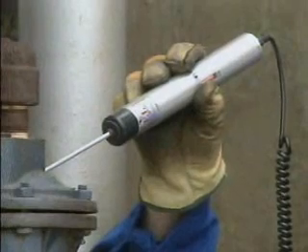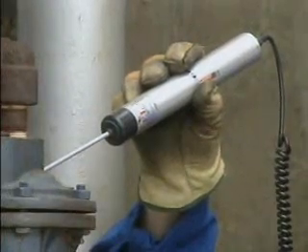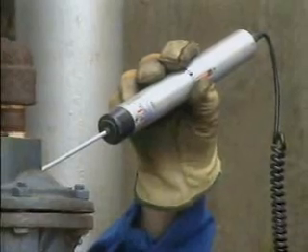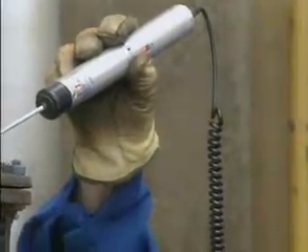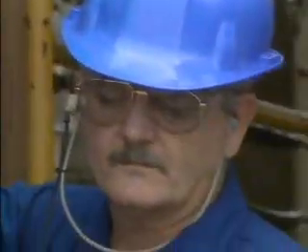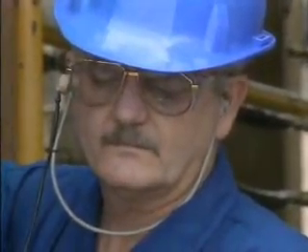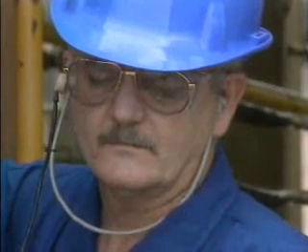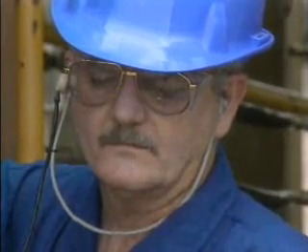Also, when an ultrasonic detector is used to inspect a steam trap, the frequency response of the detector may vary by model and manufacturer. These variations can affect the actual sound that you hear from a trap. But listening to a few examples of typical trap sounds will give you some guidelines that you can apply on the job.